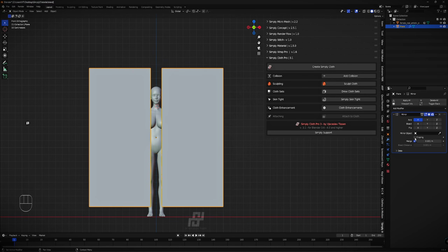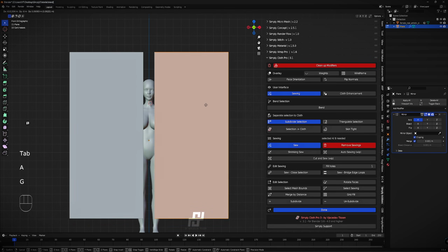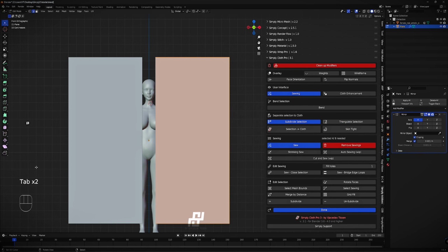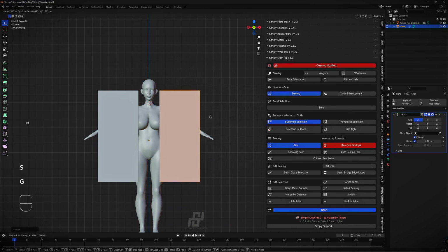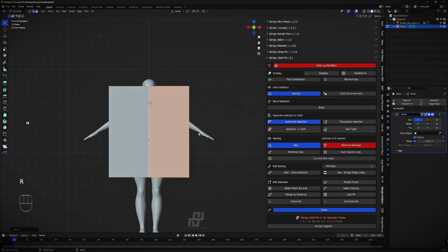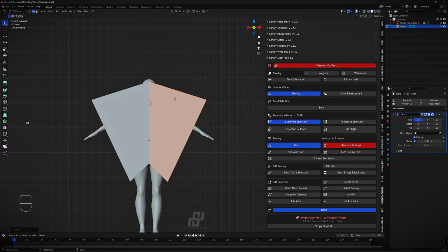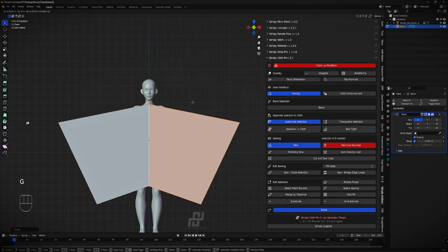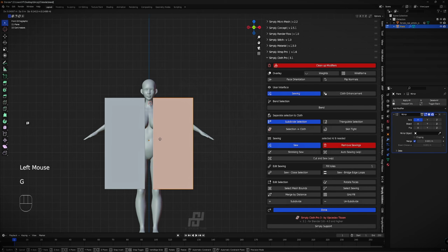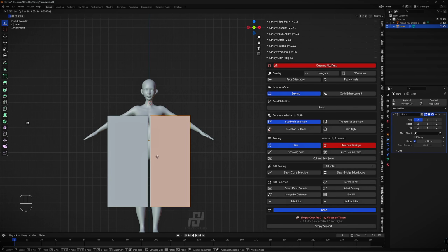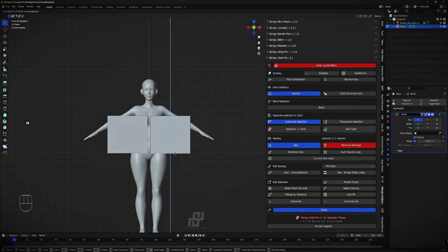So here I like to check the clipping checkbox. So if the object is going in edit mode, like if I hit Tab, I can switch to edit mode and object mode. I go to edit mode, and if I merge them here together, it is merged, you see? It is now not separated anymore, it's like one object. So I don't want this at this moment. I just want to make it separate like this. And now I can check it on.